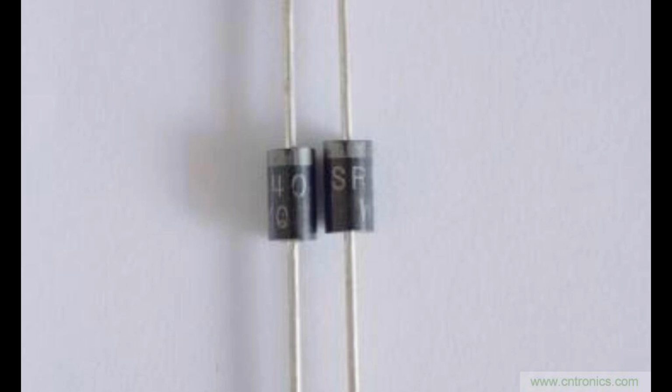Advanced semiconductor materials. The use of high-performance semiconductor materials with superior electron mobility can enhance switching speed. Optimized circuit design. Careful design and layout of electronic circuits can minimize parasitic capacitance and inductance, enabling faster switching. High-frequency operation. Devices designed specifically for high-frequency applications are optimized for fast switching.